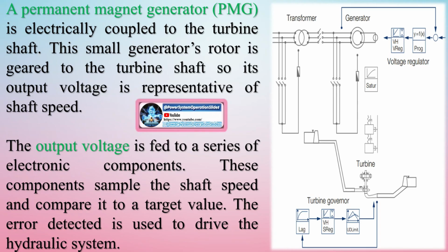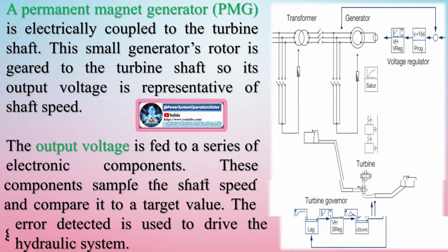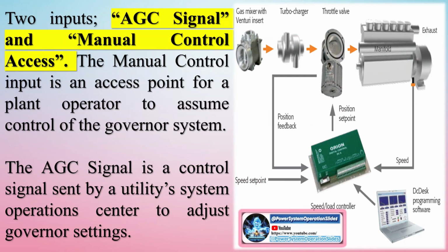As power systems became more complex, particularly in the field of electrical power generation, governors needed to respond faster and with greater accuracy. Since the 1970s, electronic governors have largely replaced mechanical systems, providing improved performance by using sensors and microprocessors to control not only speed and load but also parameters such as exhaust emissions and generator synchronization. These electronic governors are capable of controlling multiple engines, turbines, and generators in parallel, enabling more efficient power management.